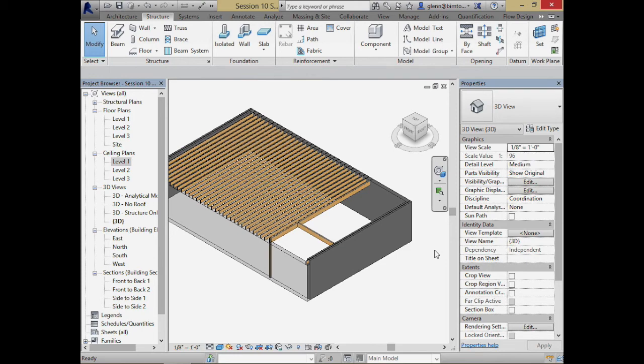And as soon as you cross that threshold, actually 2,000 sounds off, that's 1,000. Go look it up. As soon as you get higher than a certain level, it's back to that shear thing that we talked about once. These things are typically resting on a little double wooden top plate. As soon as that shear gets so high that it would penetrate and go cutting through, it's time to put some support there. So that's the general rule.